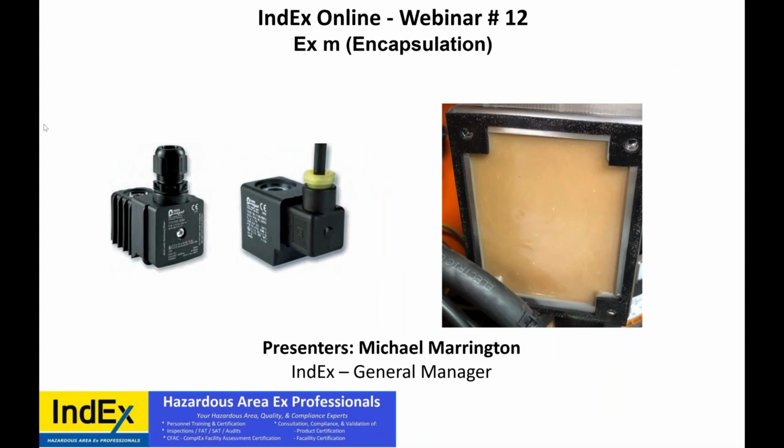Okay. Index Online, webinar number 12, EXM, Encapsulation. So what are we talking about? We're talking about pieces of equipment that have some type of encapsulant that has been poured and dried inside of it, and it acts as a means to keeping hazardous atmospheres out, dissipating heat, and making the equipment safe for use in hazardous areas. By the way, these are solenoids. This is a terminal box that has now been turned into an EXM terminal box. So let's jump into it.